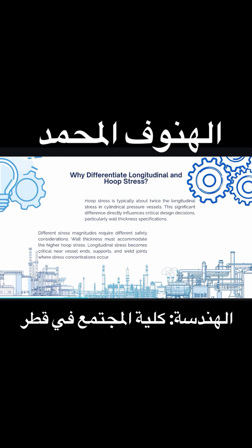Different stress magnitudes require different safety considerations. Wall thickness must accommodate the higher hoop stress. Longitudinal stress becomes critical near valves, supports, and weld joints, where stress concentrations occur.